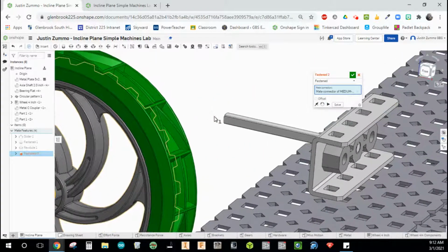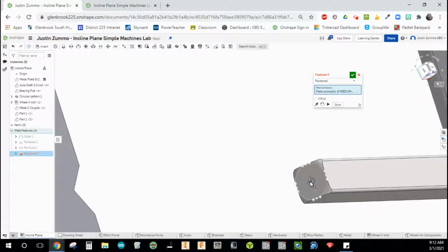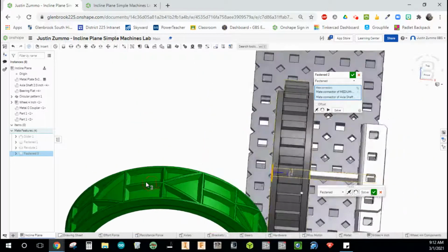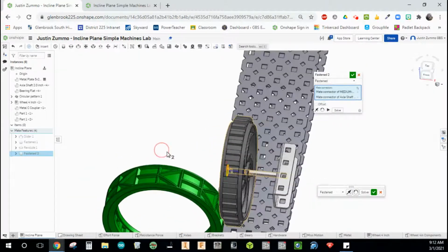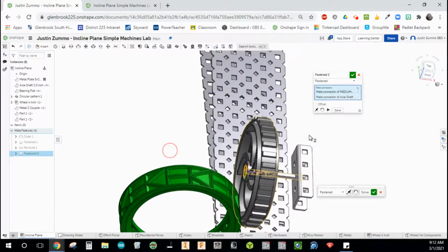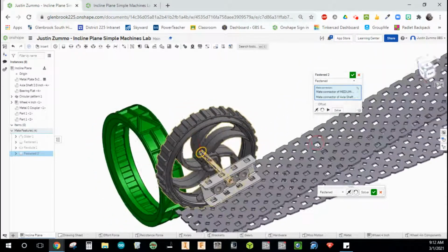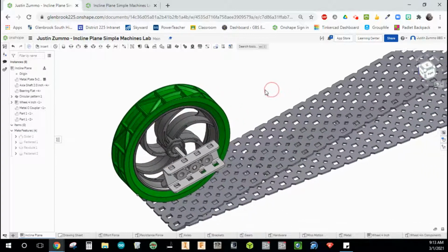And then on my axle, just rotate so I can get this edge, center point right here as well. And it actually went all the way into the wheel just like I wanted it to, so that's perfect. No offsetting or flipping here. If your wheel ended up on the outside, just flip it so that it's not virtually hanging off the edge of the shaft, and that should be good. Let me hit the check mark here. The green tire part will come with it.